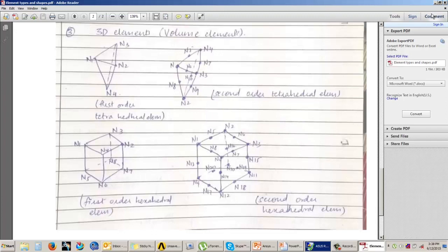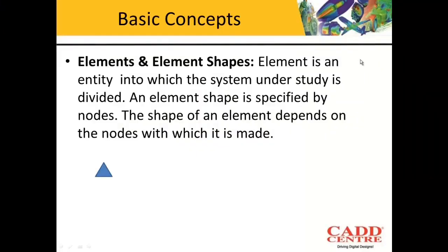The one more factor that is remaining is connectivity. Connectivity is nothing but we need to understand whether the model is properly connected or not. There should be no overlapping geometries, neither there should be gaps in the geometry that we are analyzing. Hence, whenever you create a model in a CAE software, or whenever you import a model in a CAE software, you need to first check the connectivity of the model, whether they are intersecting or whether there are gaps. So that is another factor that has to be taken into account when you start meshing, that is connectivity.